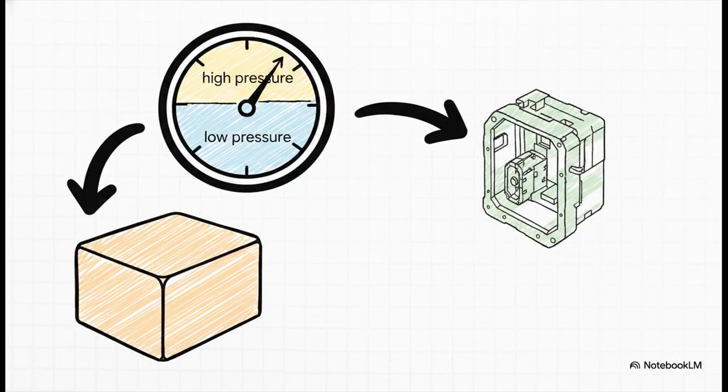Once the resin is perfectly dry, the melt enters the mold. Now, your injection pressure needs to sit firmly in the 70 to 130 megapascal range. Your part's specific geometry is what dictates exactly where you land on that spectrum. If you're designing really thin-walled, complex housings, you're going to need to push toward that 130 megapascal upper limit just to ensure complete cavity fill. But if you've got thick structural components, you want to drop to the lower end.